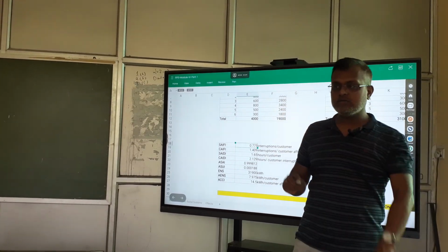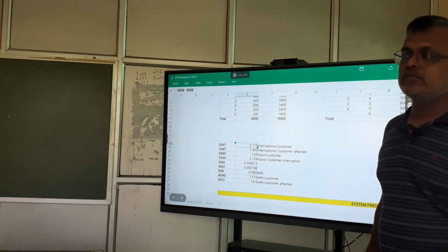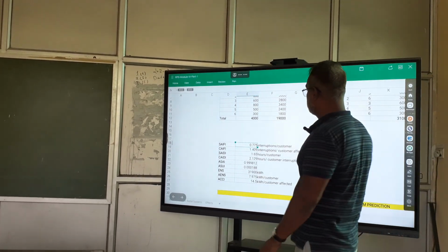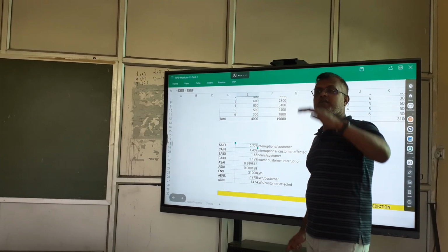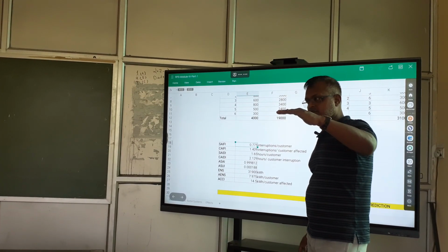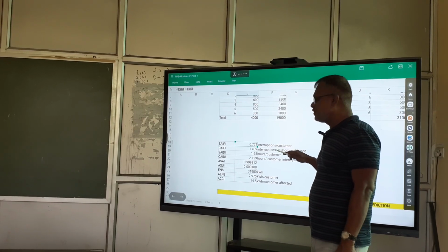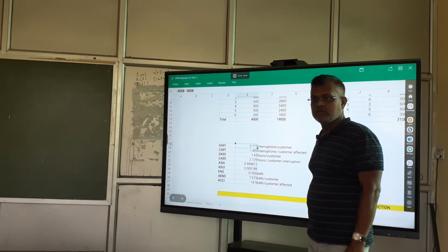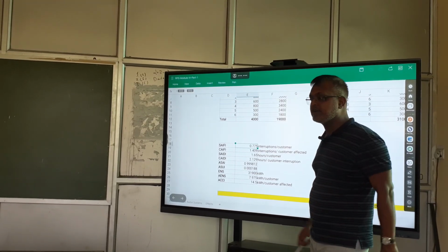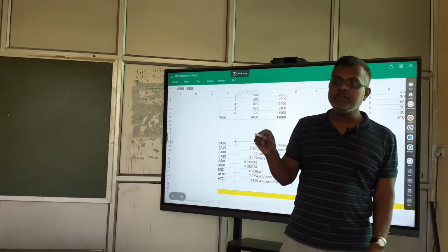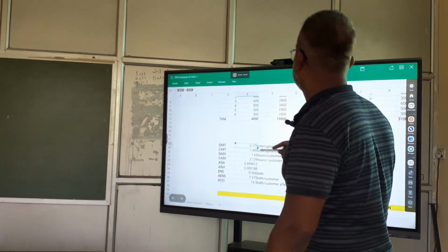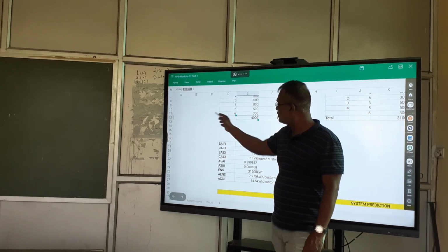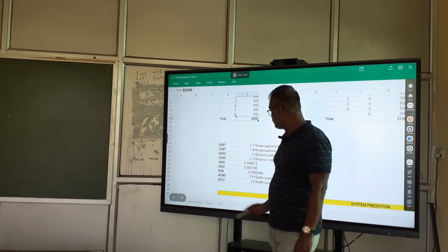From the presentation, read out the numerator: total number of customer interruptions, divided by total number of customers served. That means the denominator should be 4000. So write down 4000. Denominator is 4000.